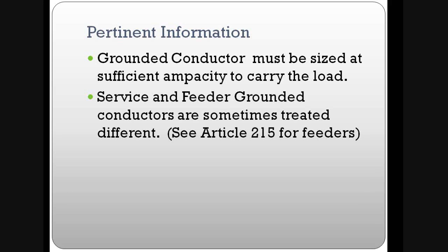Service and feeder grounded conductors are sometimes treated differently. Article 215 addresses feeders, so we need to pay attention to that. If the question is asking for a feeder that's not a service, then we might need to go someplace besides Article 250. Article 250 for the grounded conductor is going to talk about the service conductors.